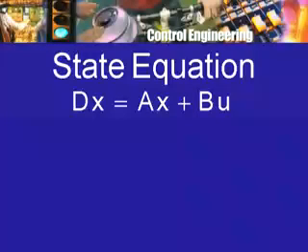and in case we are going to treat the load torque as a disturbance variable, we might write this bu into two parts, that is the input u may be split into two parts, the armature voltage input and the disturbance input. For the moment, let us put them together. So, x is a vector, u is a vector. This x vector will consist of what?